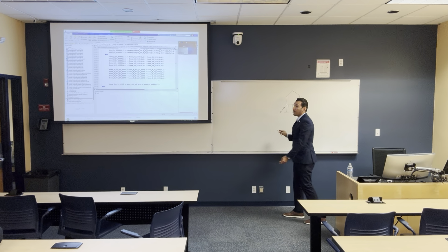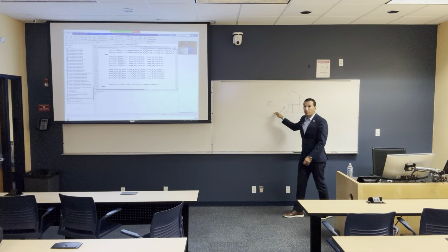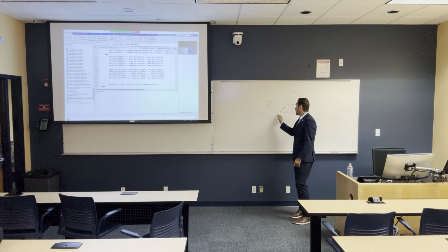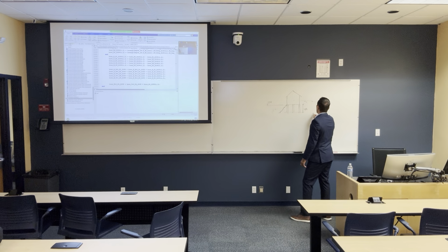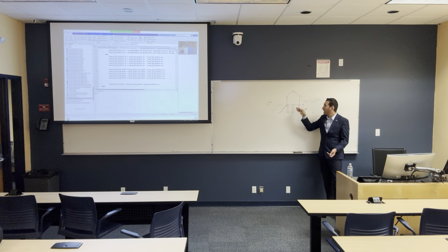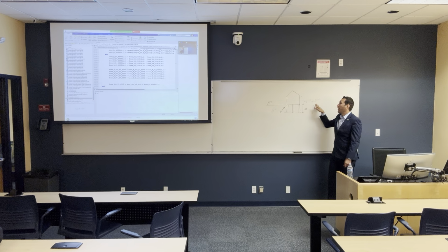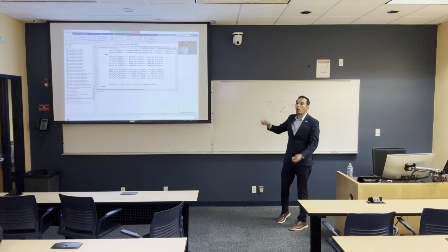All I care about in this case is the FFE, right? If I have the FFE right, and I have the ground elevation right, and I have the water surface elevation right, that's it. You don't have to model anything. You just have to input the FFE, model the ground elevation, and model the water surface elevation. So in terms of mitigation, I don't have to do all this stuff.